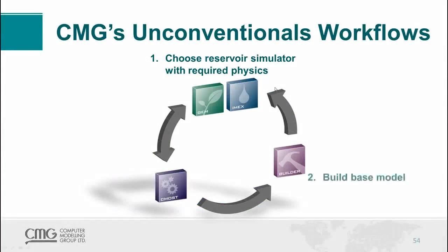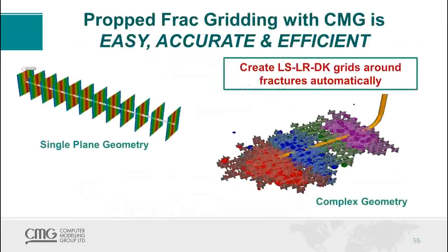So that's step one. The next step in the process is to build a base case model, and that's where Builder comes in. With Builder, we make it very easy to bring in your geologic model or to create a geologic model in Builder and then apply the necessary gridding to represent planar or complex fracturing.